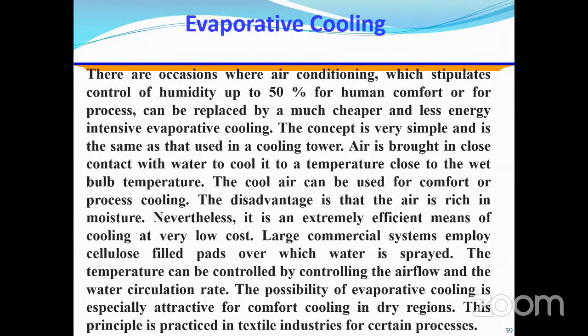Evaporative cooling. There are occasions where air conditioning, which stipulates control of humidity up to 50% for human comfort or for process, can be replaced by a much cheaper and less energy intensive evaporative cooling. The concept is very simple and is the same as that used in a cooling tower.